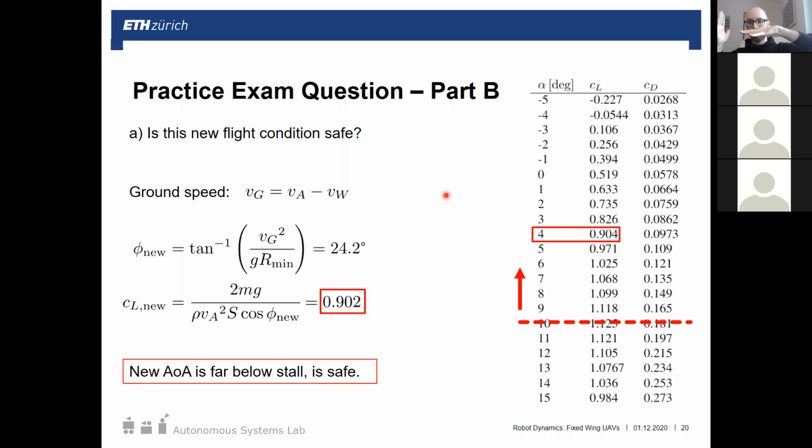As soon as that air mass is also moving, as I'm still flying inside of it, then relative to the ground, I'm going slower, right? Because I'm flying at the same airspeed within that box of air, but that box of air is also moving me at some constant velocity in a different direction. So you sum the two: the airspeed vector and the wind speed vector are summed to get ground speed.